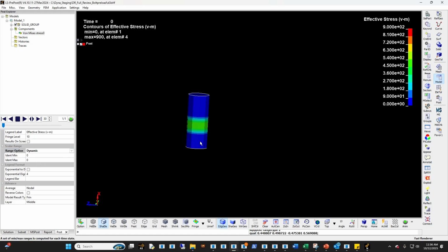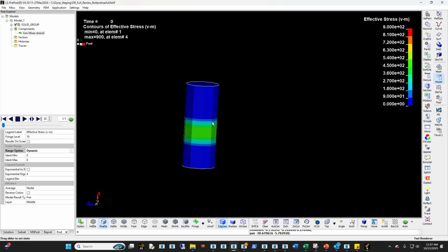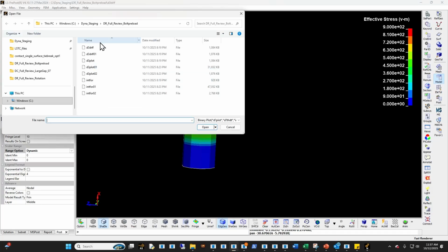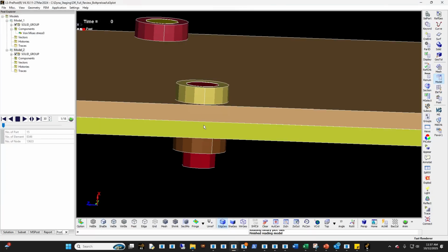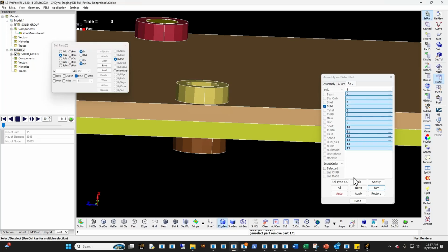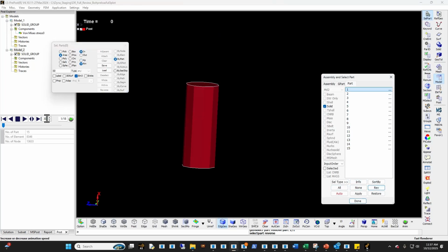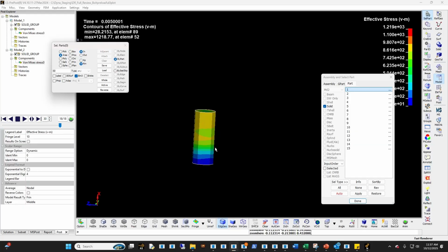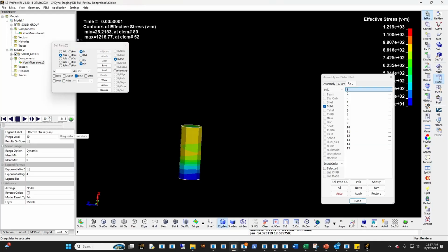Yeah, so you can see there is a dynamic, a pre-stress that's added in the bolts. And if you want to take this to the full transient analysis, you can see the same thing in this case. If I reverse it, then you can see the stress on the bolts, which is going to be a little bit different, right? Because this is the beginning point, and then it's going to basically load it.